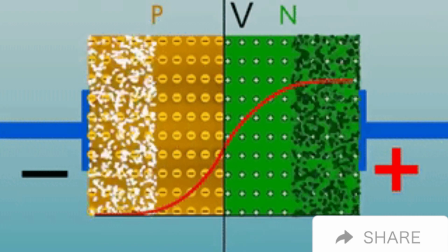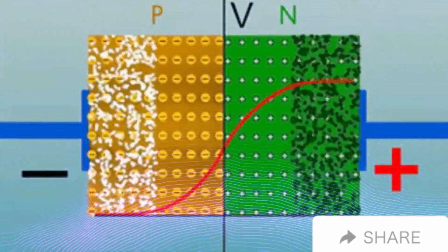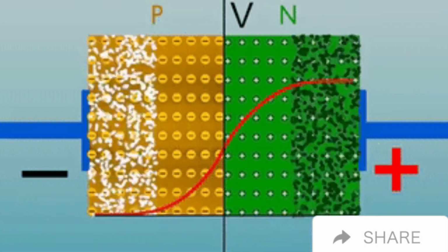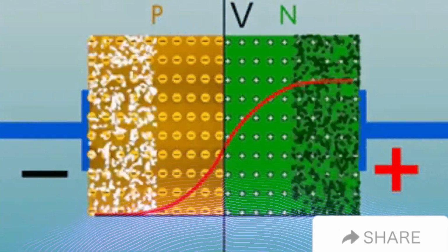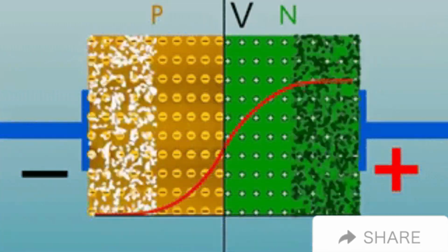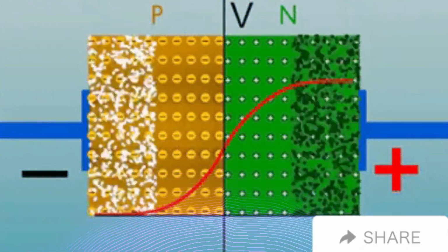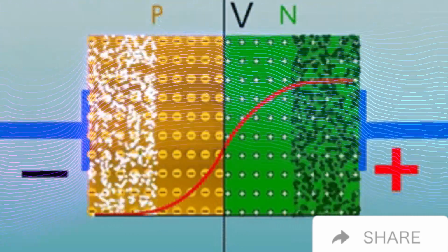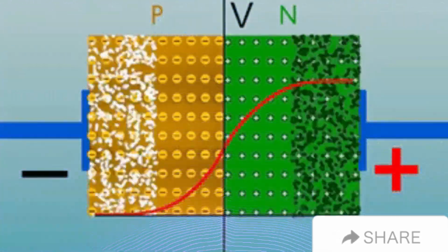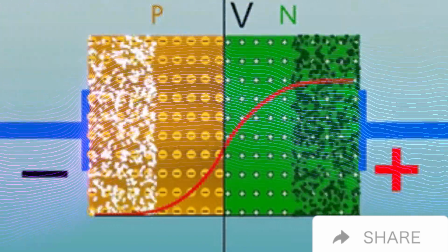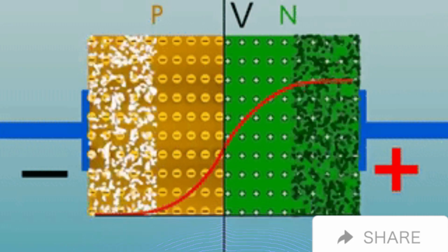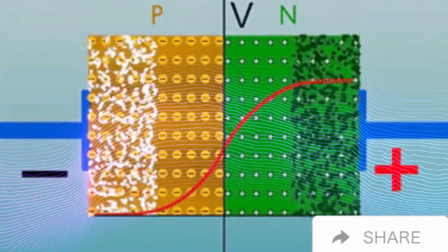The p-n junction diode has many uses. First and foremost, probably, is the use for rectification, but it can also be used for signal demodulation. Diodes are used to recover original modulation signals from AM or FM modulated waveforms.